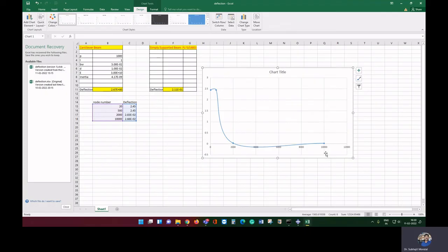If you don't have that exact solution, then what you can do is more trials using 20,000 elements and then 50,000 elements, and you have to see whether your result is changing or not. If you see that your result is not changing after 20,000 or 50,000 elements, then you can stop somewhere there and you can carry on your analysis in ABAQUS.